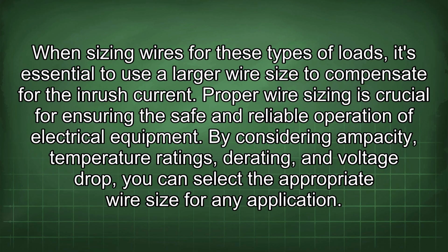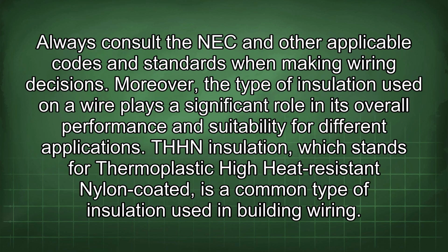By considering ampacity, temperature ratings, derating, and voltage drop, you can select the appropriate wire size for any application. Always consult the NEC and other applicable codes and standards when making wiring decisions. Moreover, the type of insulation used on a wire plays a significant role in its overall performance and suitability for different applications.